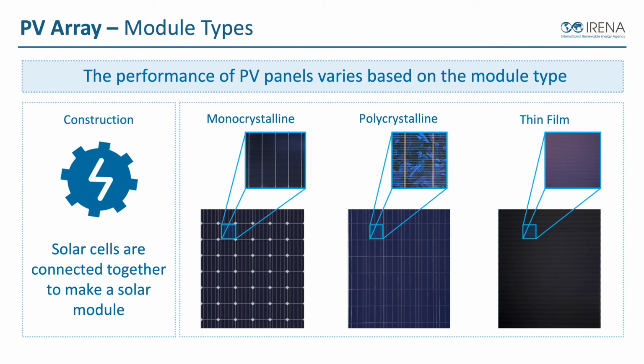But in practice, sometimes the difference is not actually in monocrystalline versus polycrystalline. It's in manufacturing types, in the different ways that manufacturers all over the world take those silicon-based solar cells and manipulate them to try to get better efficiency. The majority of the world's solar, which is mono and polycrystalline, is going to live somewhere between about 15% efficient on the low end, and right now about 22% efficient on the high end for commercially viable products.